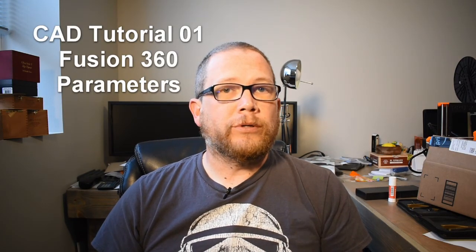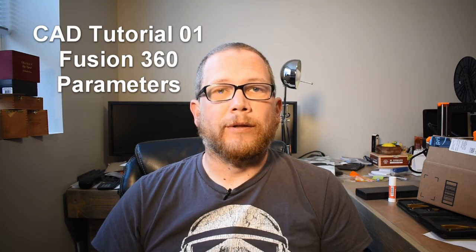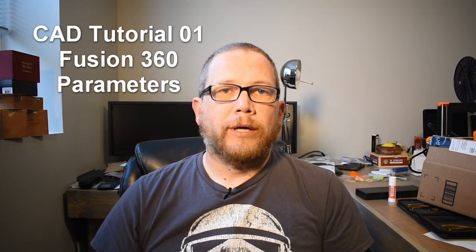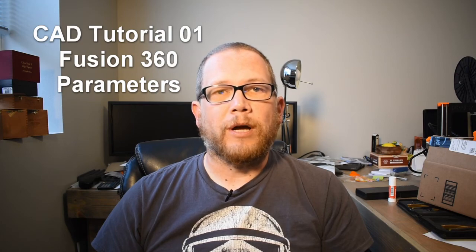Tutorials are something that I want to do as well, and so this is going to be our first tutorial. It's in Fusion 360 and we're going to talk about parameters. And parameters are really a cool thing. I mean, the essence of parametric modeling is the fact that you use parameters instead of dimensions. It makes your models a lot more flexible, and it really allows you to drive those models with those parameters. So I'm going to explain a lot more about that in the tutorial. So here you go. Enjoy.